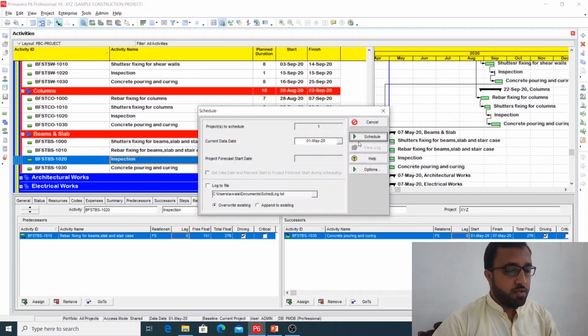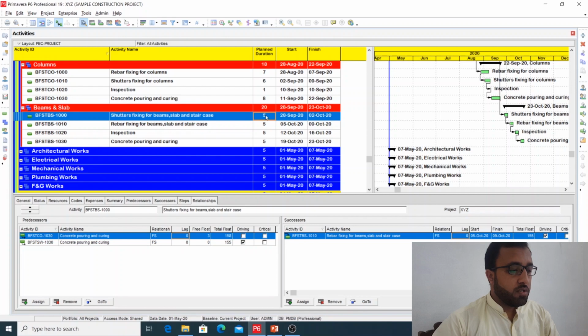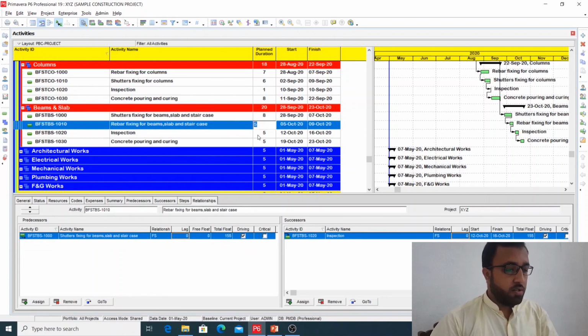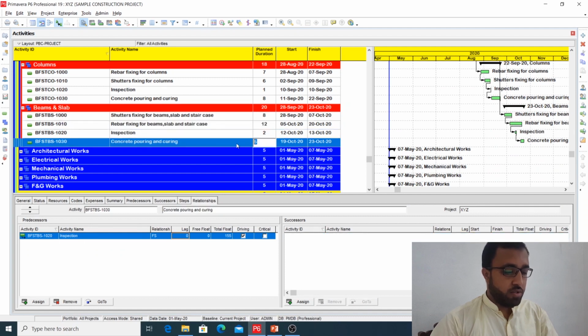Then we will go here, schedule it, and give shutters 8 days, rebar fixing 12 days, inspection 2 days, concrete pouring 8 days.